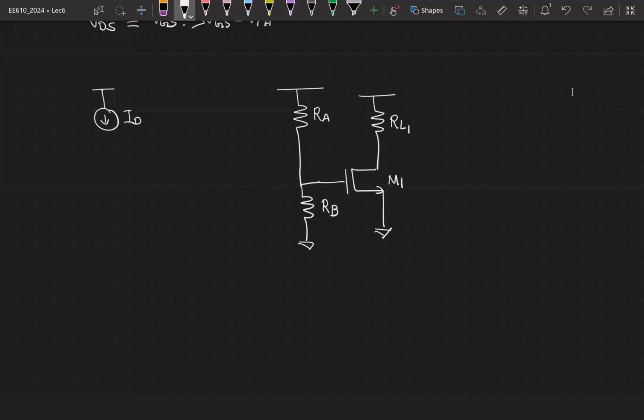I have also figured out this contraption where if I connect the drain to gate of the transistor, I am guaranteed that the same reference current is going to flow through the transistor. Now, can you recommend some solution wherein I could replace the voltage here such that the same current IRF is flowing through this? Is that clear? What is the voltage here? This is the required VGS0 now.